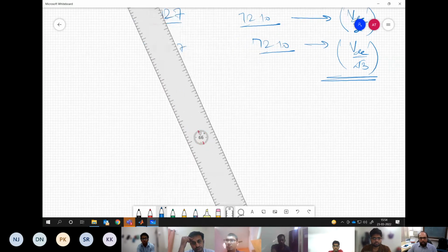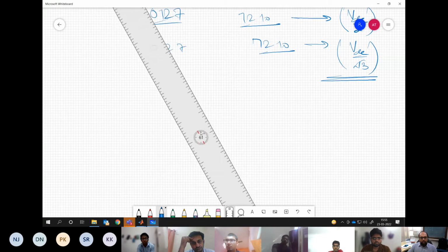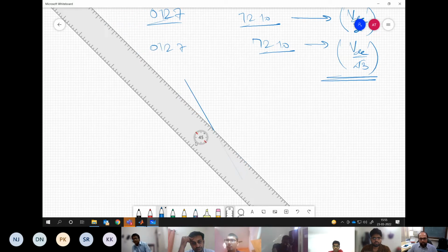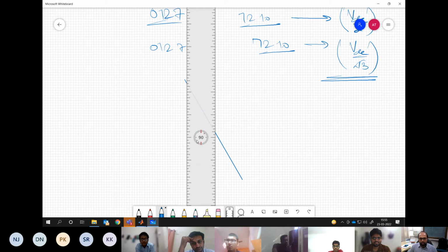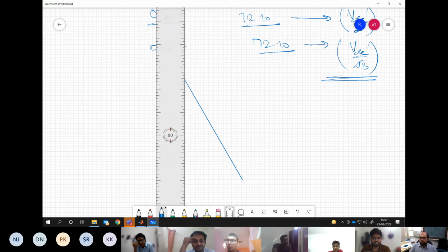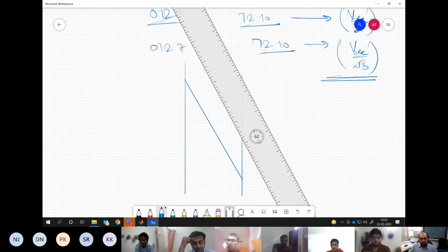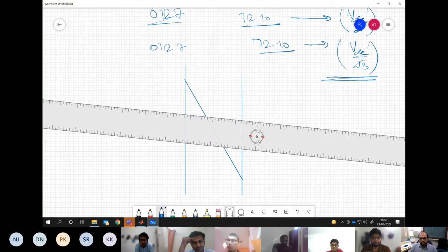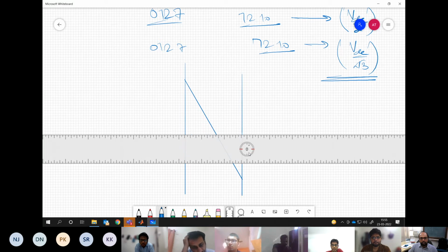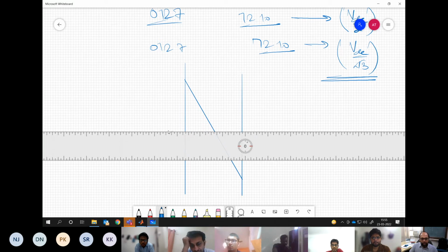Now, do you understand that this is not equal, or are you just saying it because you have heard it somewhere? If we analyze from the three-phase waveform, when the R phase is at maximum peak, at that instant the other two phases are not at negative maximum. That's why the zero voltage duration is not coming equal. In fact, it is true for any duration. It's not necessary that you analyze for the peak value only.